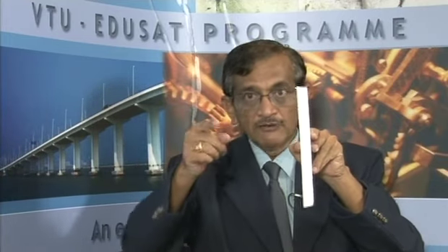Problem is clear? I will repeat again. This is a portion A to B. This side you have water up to this level, again it is a rectangle and water. This side glycerine is there up to this point. The specific weight of the glycerine is given in the problem, 15,300 Newton per meter cube, and he is asking you what is the resultant force acting on this AB.